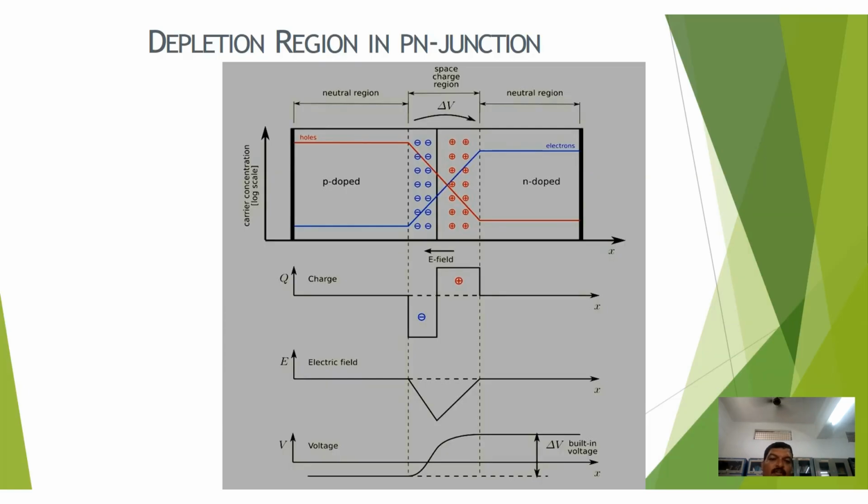When a voltage of more than 0.7 volt is applied to the PN junction diode, the holes in the p-type semiconductor will move towards the n-type, and electrons in the n-type semiconductor will move towards the p-type, so that the flow of electricity takes place.